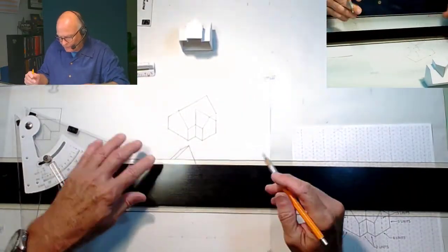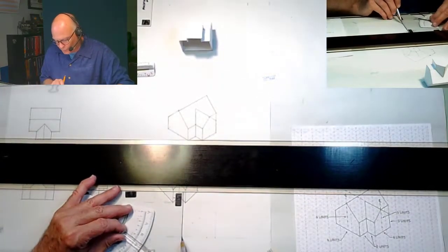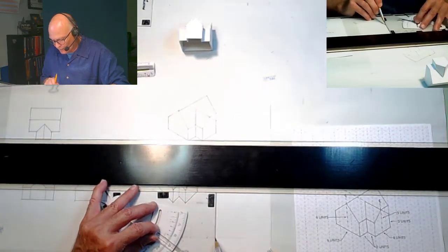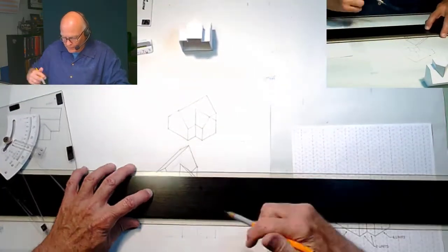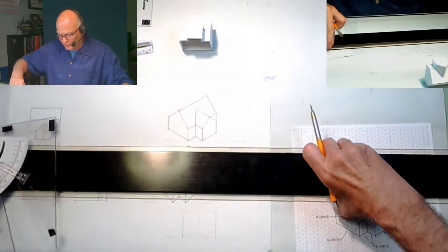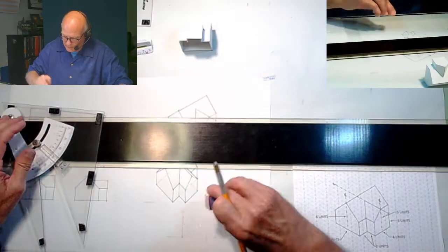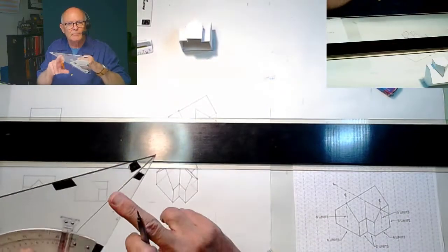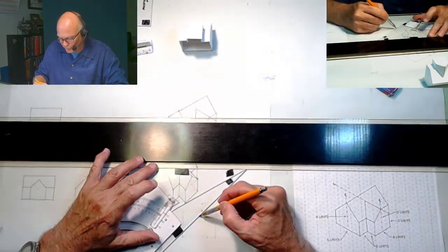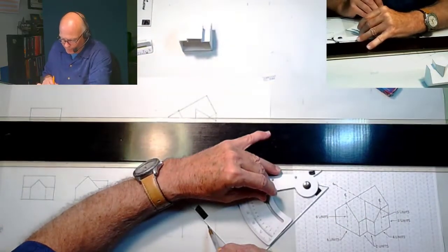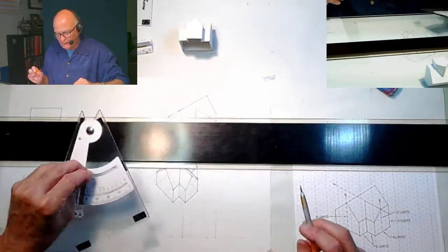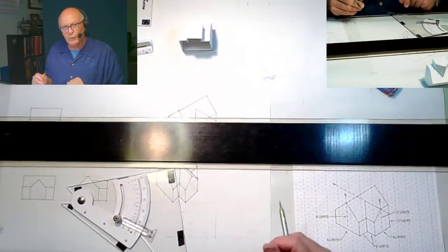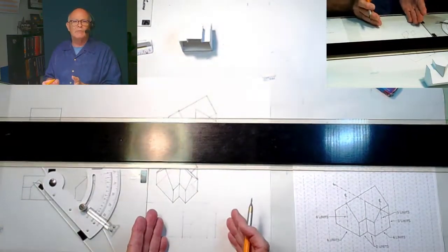Now, that's the basic box. Keep it light because we're going to erase some of these lines. This is going to give us some orientation on what this elevation oblique is going to do. Then I'm going to come across here and give myself the 3-foot horizontal line. And we're going to go ahead and change our triangle just for a moment. We're going to use the 45 to pick up that very front gable piece. Again, keeping it light because we know the things are going to project back and forward and project forward from them. Okay, so that's our basic drawing.